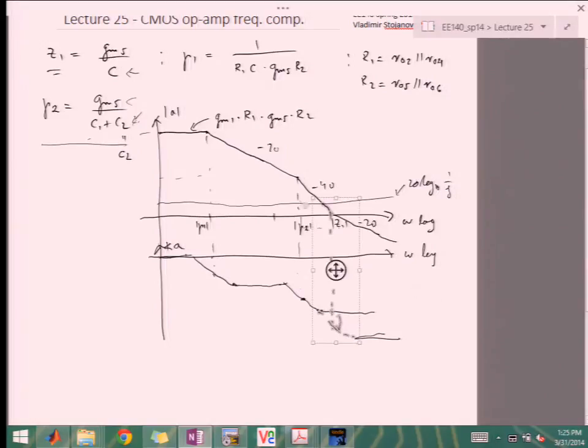If you want this crossing to happen at the shifted P2, then our shifted P1, as P1 moves this way, let's say this is the new P1 location, it would have to be parallel. And let's say this is P2 prime. Previously, P2 was here, so P2 shifted this way, and P1 shifted that way. And then the zero started going from here and shifting this way as we start increasing the C.